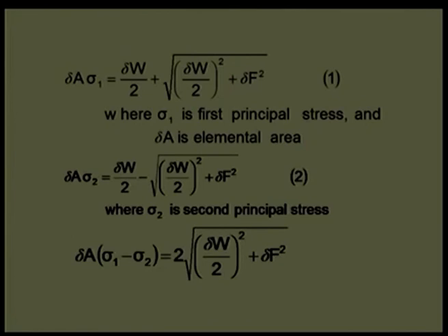So we subtract and we get an expression something like this. You can see there is a normal force divided by 2 plus the tangential force, and this is sigma 1 minus sigma 2, which I am saying should be equal to, or the minimum value of yield strength should be equal to this. It can be more than that, but the minimum value should be like this.